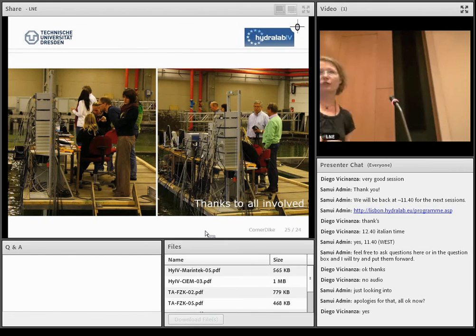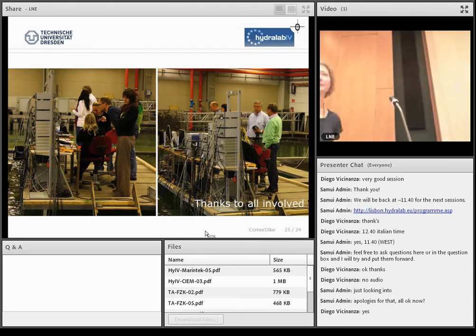I'm a bit worried about the quality of your data because of that diffraction area that you have shown in one of your slides. Was it possible to use a corner reflection method to have a wider area in your basin with the right wave conditions?